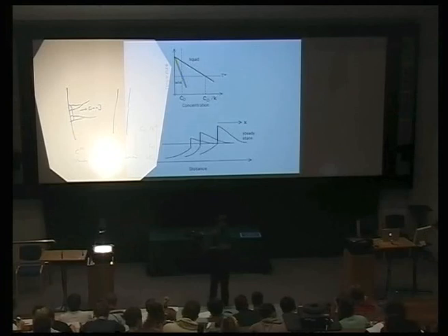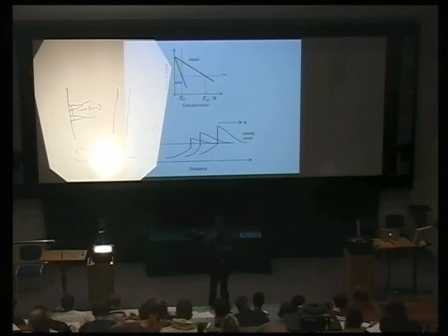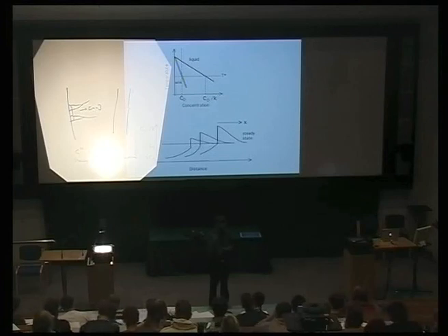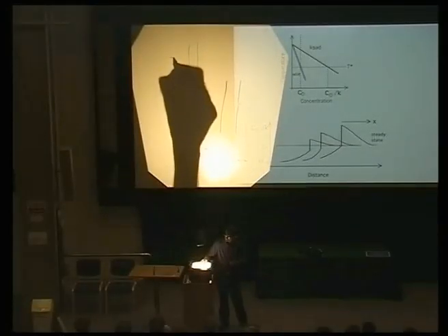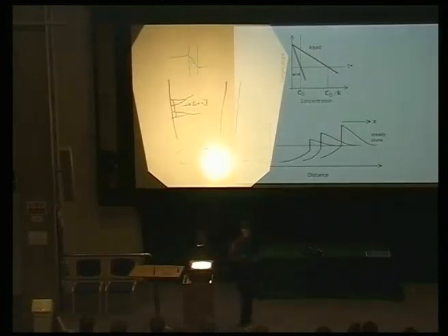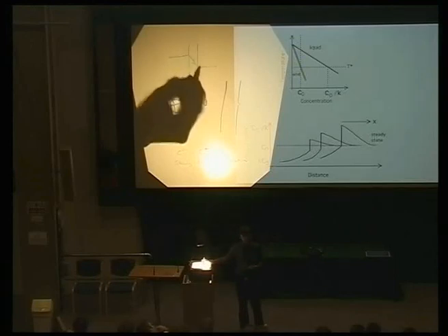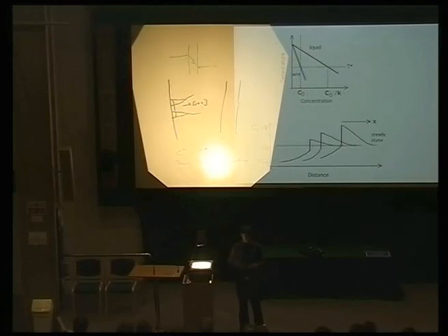Can you remember another steady state scenario that we considered in an earlier lecture? Where we had diffusion happening, and yet nothing was changing in the concentration profile. Do you remember the Fick's first law scenario? Where we had a sample of material with a constant concentration here and a constant concentration here, and diffusion happening in that direction. So if you were an observer located here, you would see no change, because these points are not changing. And yet, you are dissipating free energy because diffusion is happening.